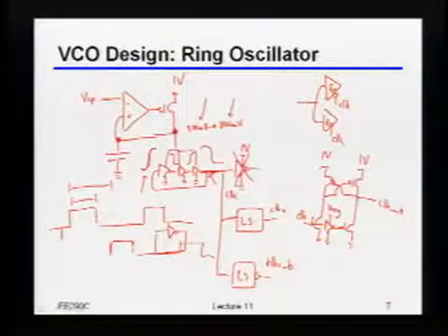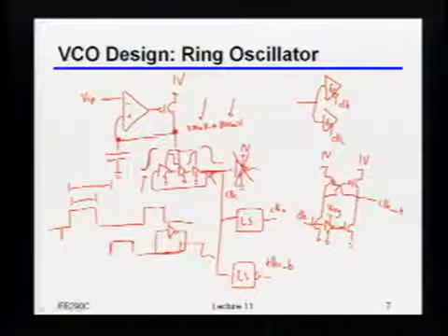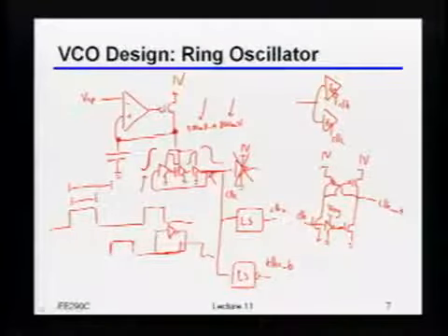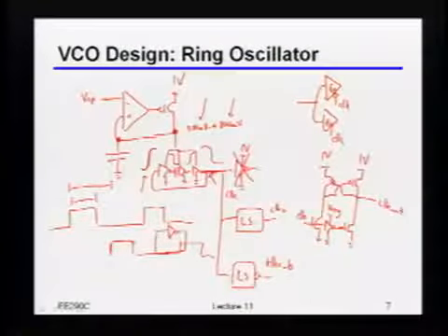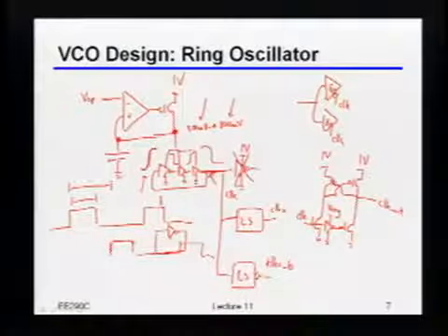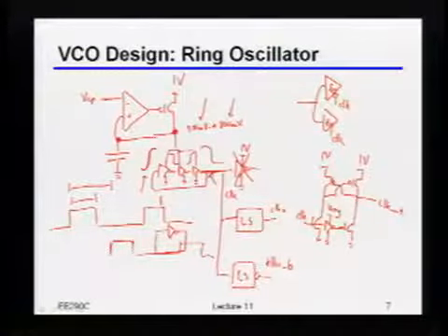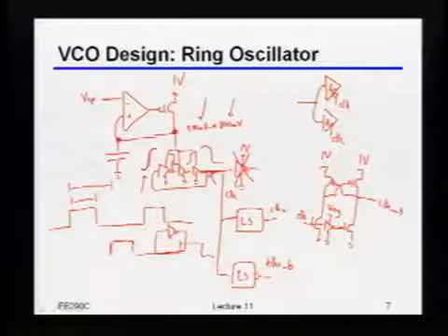Yeah, go ahead, Linkai. So the clock inside the ring oscillator is not 50% duty cycle from the beginning, right? Okay, so that depends on how you've actually built the ring oscillator. So the question was, is the clock even 50% to begin with? You're absolutely right. It may not be. Turns out you will typically try and size things so that it reasonably stays 50%, just because for phase noise that turns out to be a good thing to do. If people are interested, come bug me. I can explain why. But you're absolutely right. It may not be 50% to begin with.